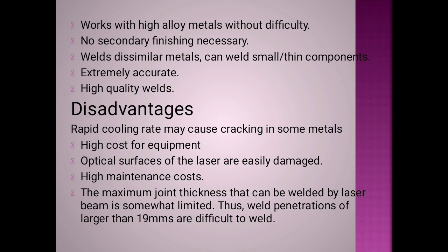Then disadvantages. It has high maintenance cost, high cost for equipment, and optical surfaces of the laser are easily damaged. Weld penetrations larger than 19 mm are difficult to weld. Rapid cooling rate may also cause cracking in some metals. So these are all the disadvantages involved in laser beam welding.